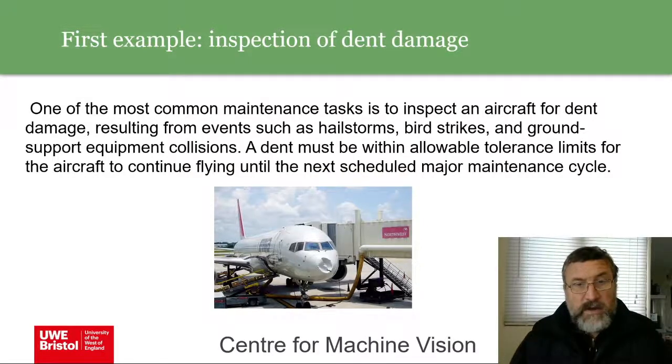You can see this aircraft has got a rather nasty dent in the front there. Things like bird impacts are more serious than people might imagine. Obviously, that's got to be replaced there. High-speed bird impacts can damage the fuselage and, of course, also damage the engines. In fact, a company like Rolls-Royce will, at some point during the development of an engine, start running it up to full power and throwing chickens into it at some rate to see how it can handle those kinds of impacts. Dead chickens, I may add. But that's the kind of thing that aircraft engine manufacturers do.